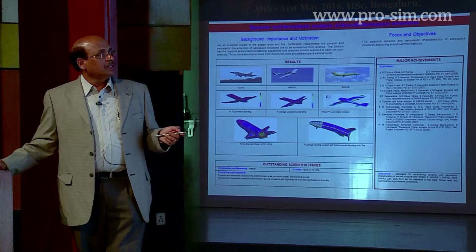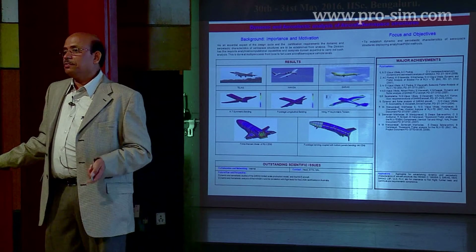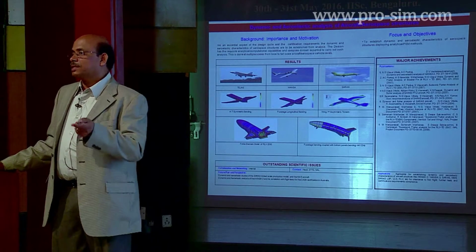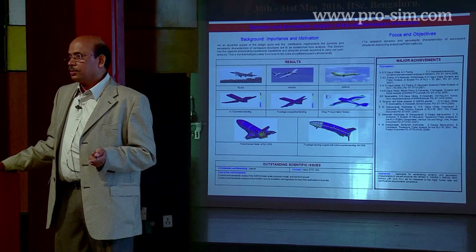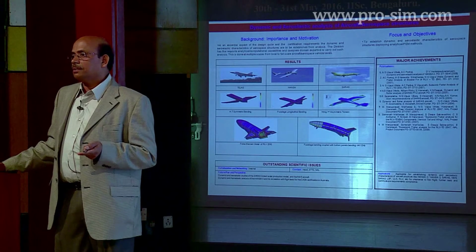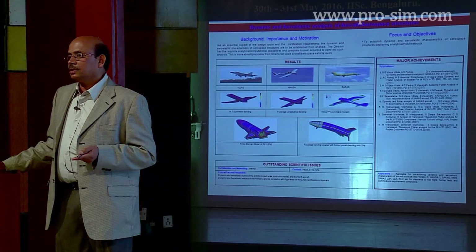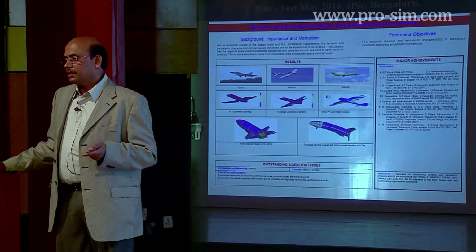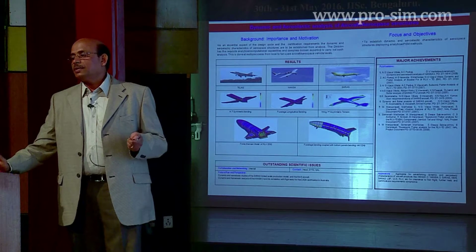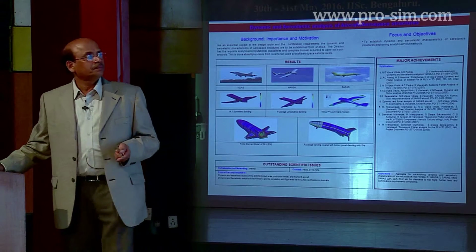Then we have also worked on the RLV. In fact, I am proud to say that we were the first to do it. As soon as the basic preliminary design of the RLV was done, that was given to us for doing the finite element modeling and simulations, to give them feedback on the design that was done. This was done by us during 2006, and I'm happy that 10 years down the lane, 1 week back, the RLV has flown, and successfully. So we did the finite element modeling and flutter analysis, everything for that. In fact, the RLV had a different kind of problems. When I come to that, I will be talking about that.